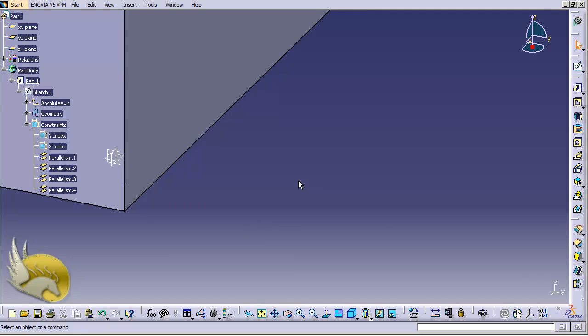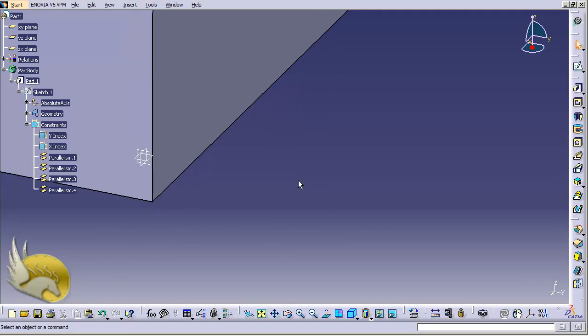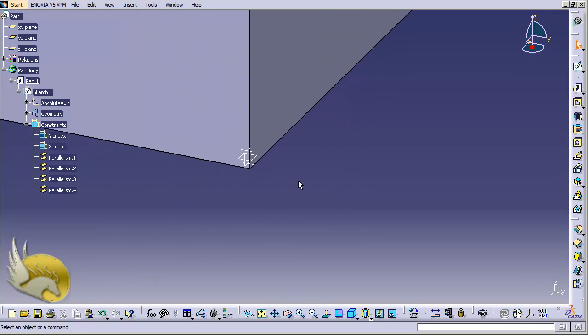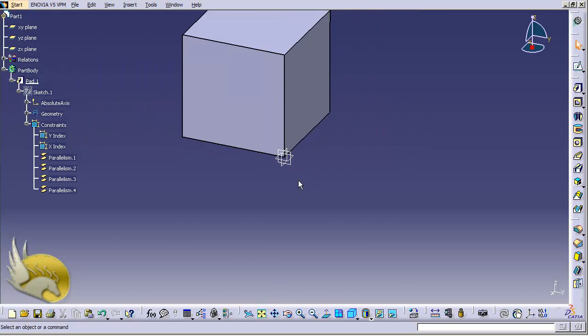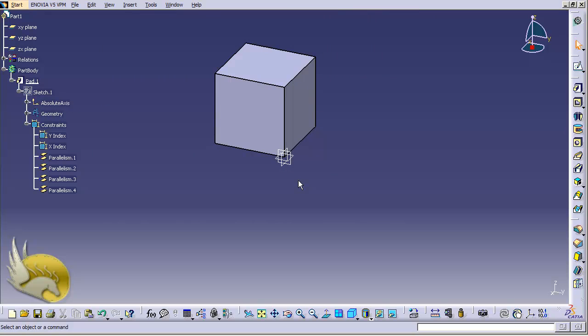Now I have to zoom this out using the control page down, and that's going to be a very big shape because I have not associated the units, but that's okay. If I added some millimeters in front of those, that would be okay. So I should add mm in front of the values so that I have the correct measures.